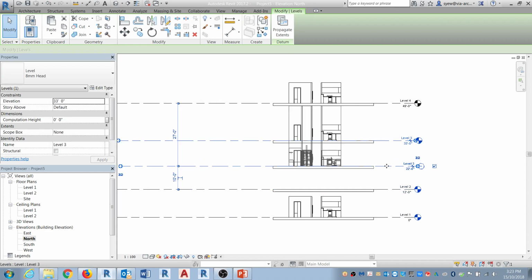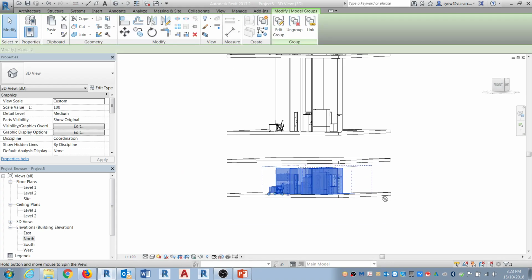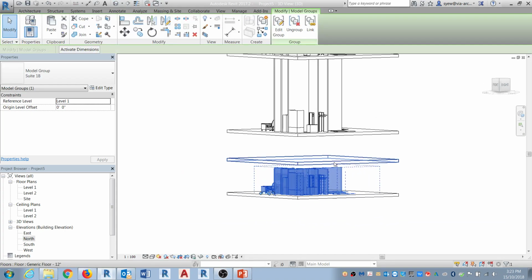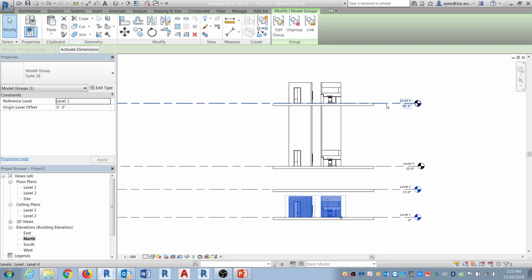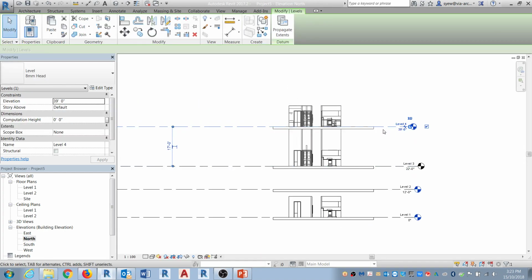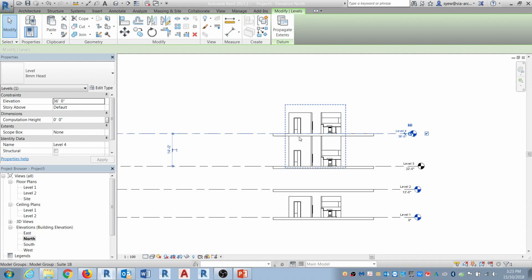So you notice that what I did is that very simply, I made the wall all unconnected, right? This one did not connect to the underside of that particular floor. And what I did here is that I just basically attached those items to the underside. And now when I flex it, you notice that it follows with the floor changes.